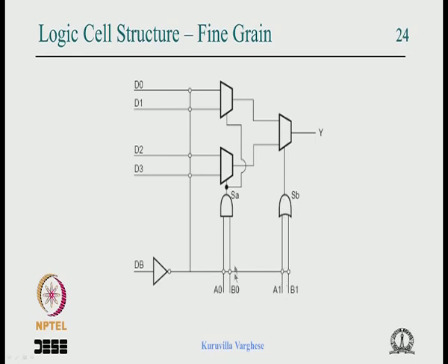So normally if you want 2, then you connect 1 to the logic 1, other uses variable, but in some cases like you give A, B, C, D, then some combination of product terms of 5 variables are possible. And you also remember that if you connect an A, B, and instead of giving 1 0 here, if you connect a third variable here like C, C bar and so on, you could make 3 variable implementation. So with this, like 1 variable here and 4 here, maybe some combination of 5 variable can be implemented, otherwise 3 variable implementation can be done.